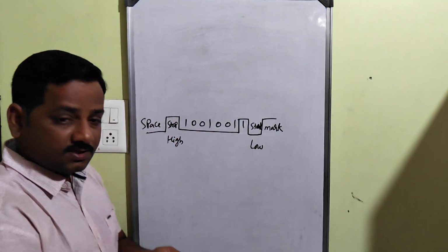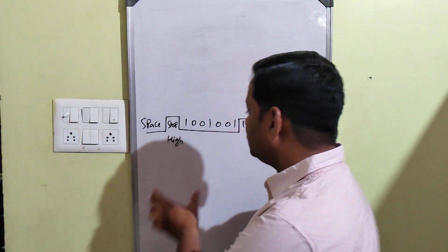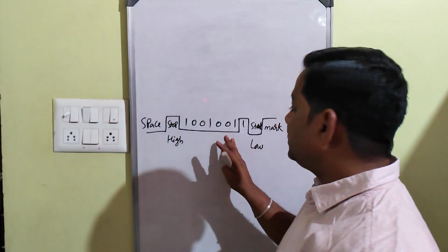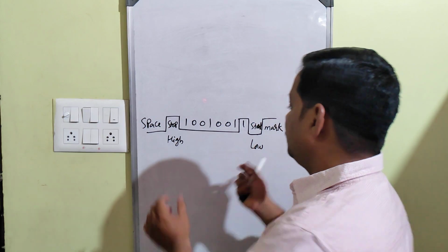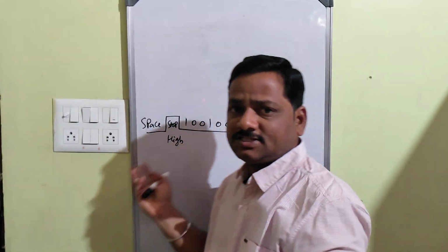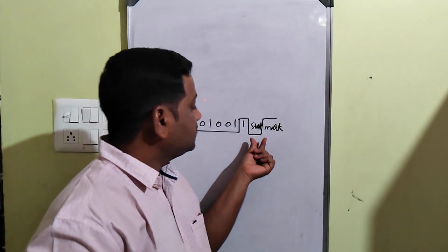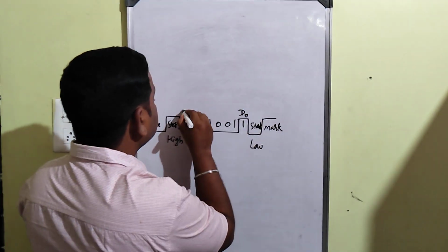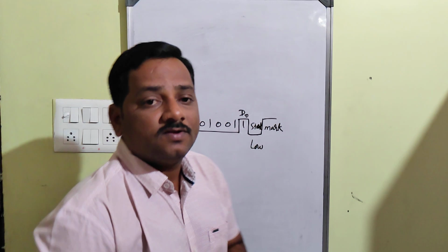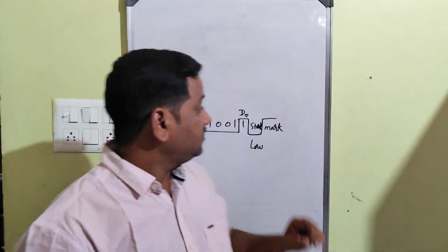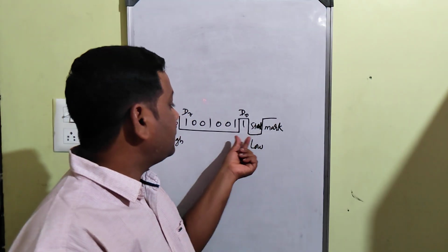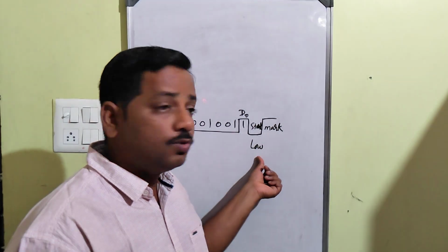See, what I have done here is I have this actual 8-bit data which is to be transferred serially, but this 8-bit data has been framed with some other extra parameters, like we have a start, means all this is D0 and this is D7. It means that whenever we are transferring data, the LSB, least significant bit, will have a start bit which is low.